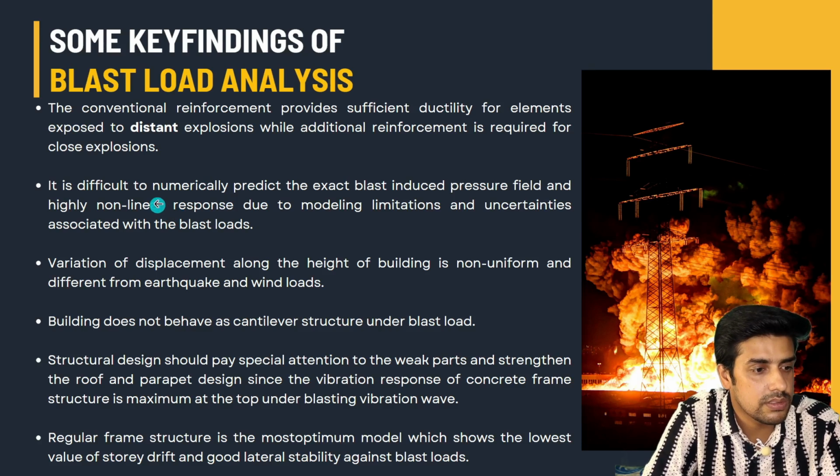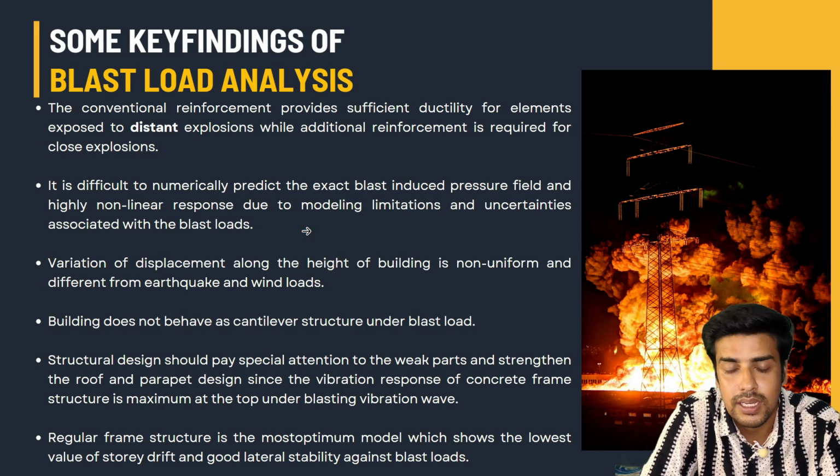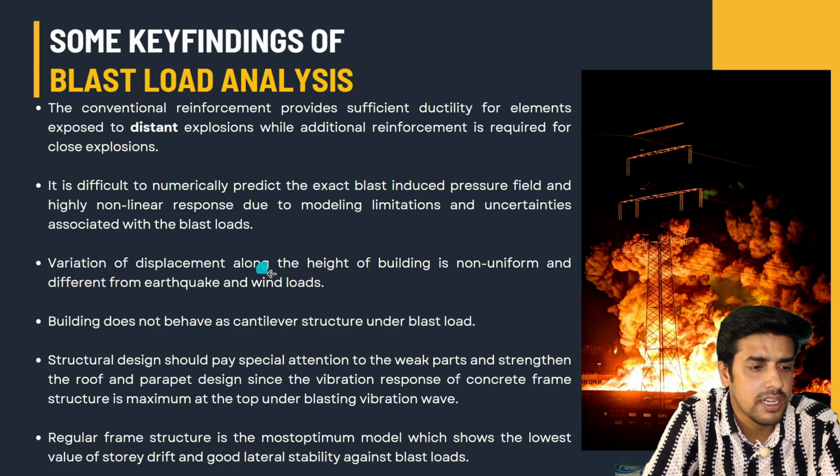Second point, it is difficult to numerically predict the exact blast-induced pressure field and highly non-linear response due to the modeling limitations and uncertainty associated with the blast load. It's obvious that the impact load can happen anywhere. It can be at the bottom story, the mid story, or the top. That will induce a non-linear response, and the software can't handle this particular thing. What we can do in software is run separate analyses by changing the height of the blast load. We can do the first analysis at the base, then at the mid and the top, and then we can do all the critical analyses.